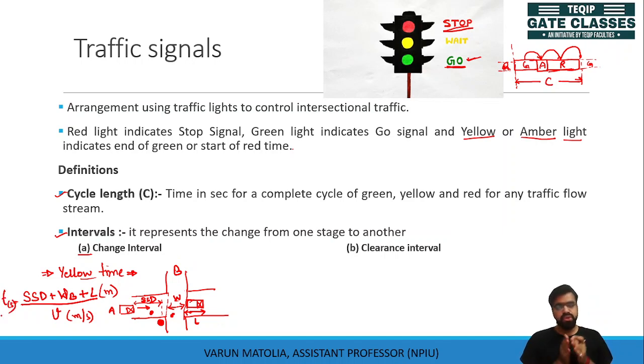So this time should be available for the driver, so that if he is not able to stop, because this is SSD, if he has just entered the SSD, he will not be able to stop before the intersection. So let him cross the intersection. That's why we provide this yellow time, so that he can cross this much distance. This is the time.